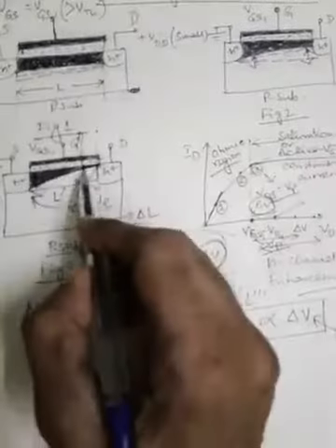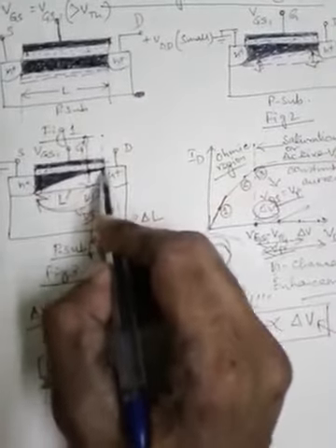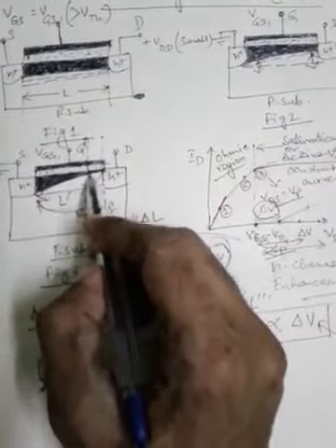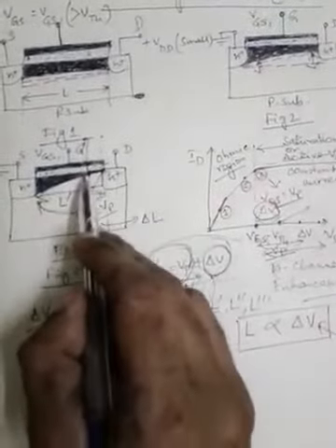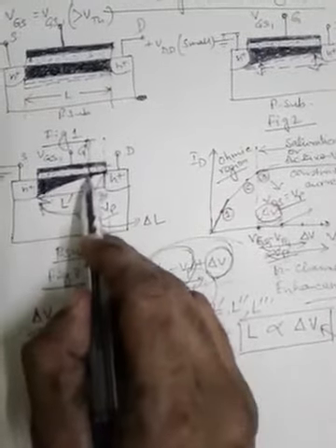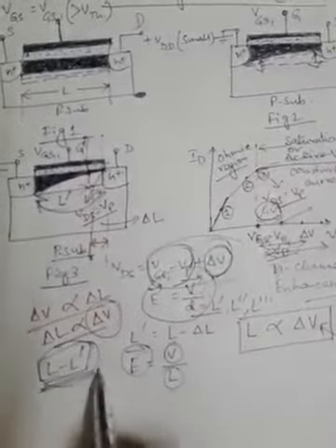So at this point, where the pinching off is now happening earlier than in the previous case, because of this increased electric field between source and drain, they will feel much more acceleration to complete their remaining journey of L minus L prime distance.